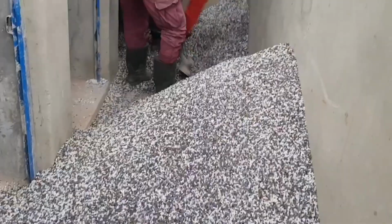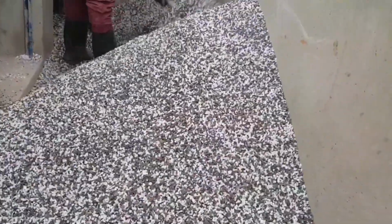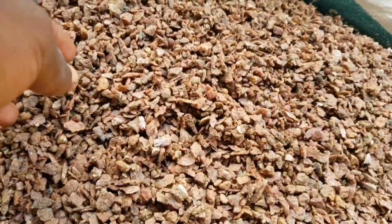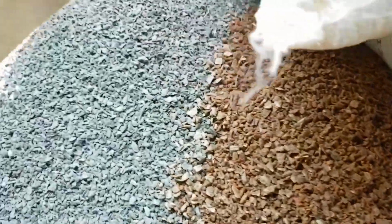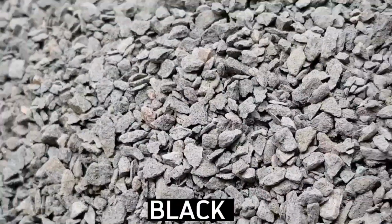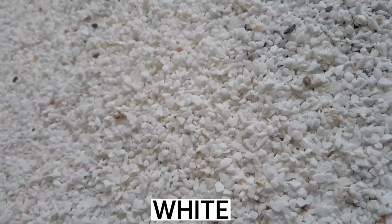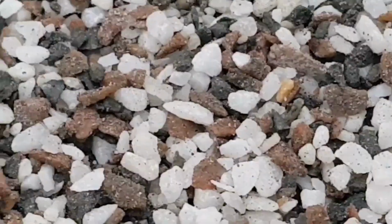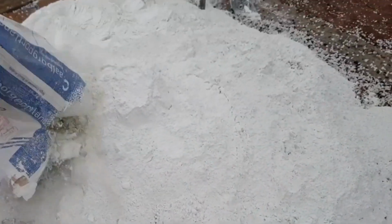During the mixing process, these terrazzo aggregates or stones come in a single color pack or bag, so we have to mix different bags of aggregates to come up with a favorite or desirable color. For example, this was maroon color or brown, this was black, and this was white color. So we mixed these 3 different colors to come up with this favorite color. After mixing to your favorite colors, add cement and mix thoroughly.